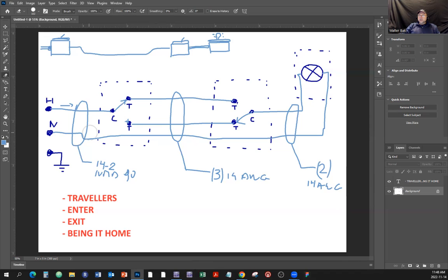So what we're going to do is we're going to have that interrupted here. So there's three wires going to be pulled in from here to here. And what we're going to do is we're going to have a pigtail right here, pigtail, okay. And there's going to be another pigtail. So now you're going to practice doing pigtails in the box, okay. Why are we doing this?